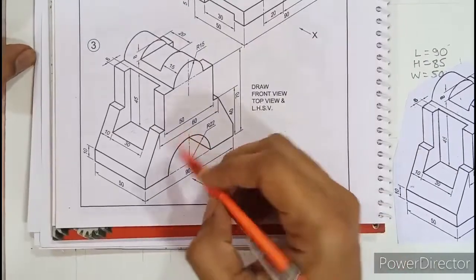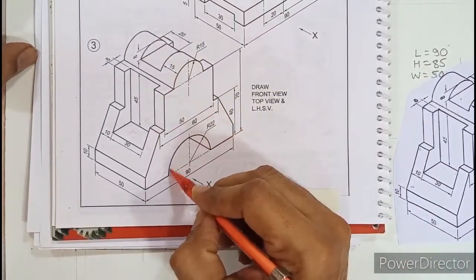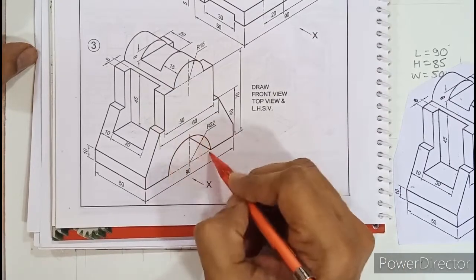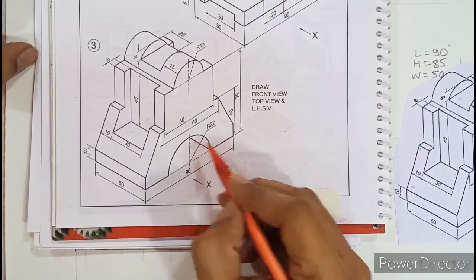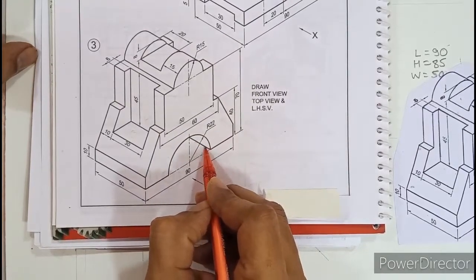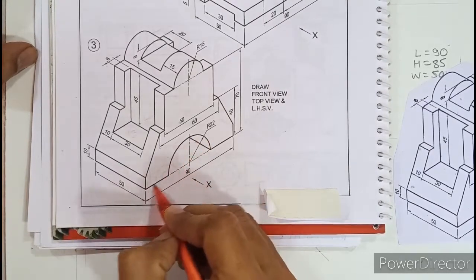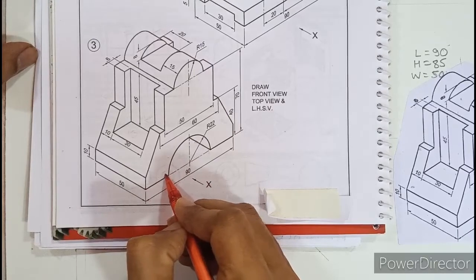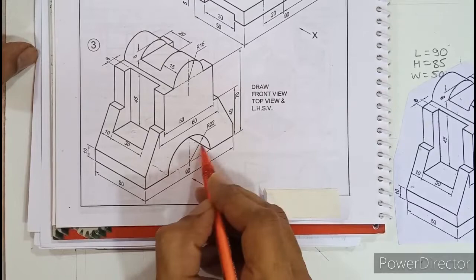On carefully analyzing the top view, the only thing left is, you can see at the bottom there is a semicircular edge. It's a cavity, and there is an edge going inside that you cannot see. So if you guess for a while, you will come to know that the first edge is here. Second edge, if you observe, look at this semicircle and this line, wherever they meet at a corner, from this corner there is an edge going inside. So there are two edges in the top view that you cannot see.